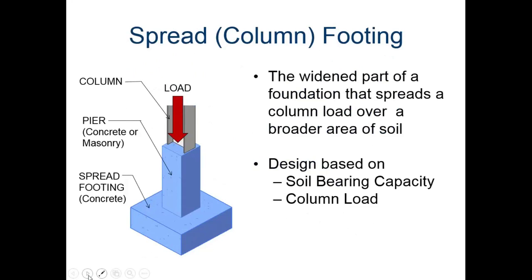Okay, so spread column footing is pretty self-explanatory. The widened part of a foundation that spreads a column load over a broader area of soil. We're just distributing the weight. It's the same idea as snowshoes. So here's our load coming down from the rest of our building, and this is our spread footing that we're talking about, made out of concrete and reinforced rebar.